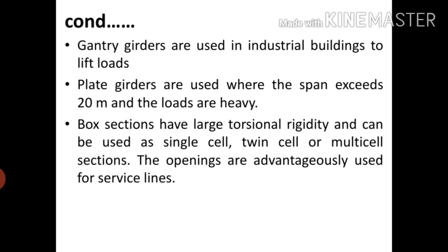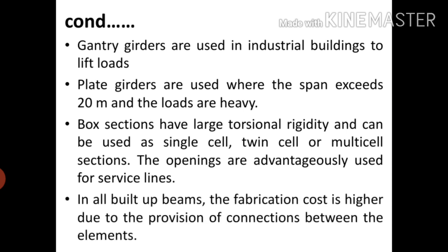Box sections have a large torsional rigidity and can be used as single cell, twin cell or multi-cell sections. The openings are advantageously used for service lines. And in all built-up beams, the fabrication cost is higher due to the provision of connections between the elements.